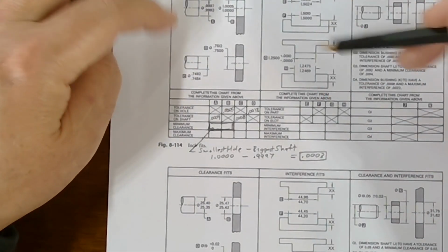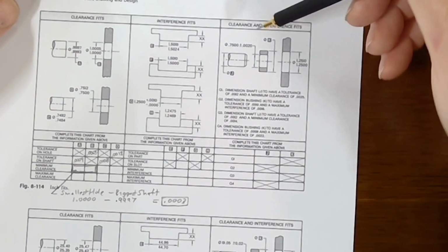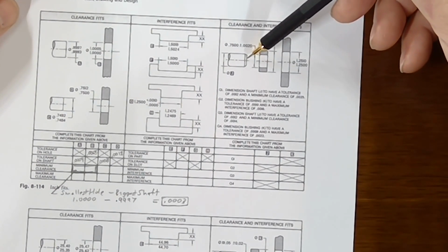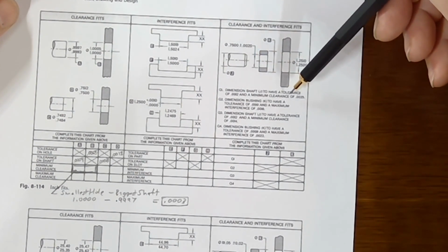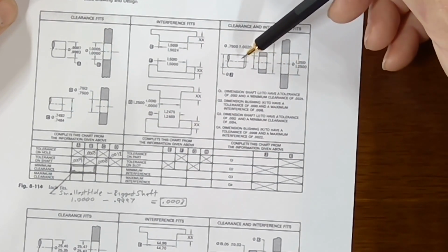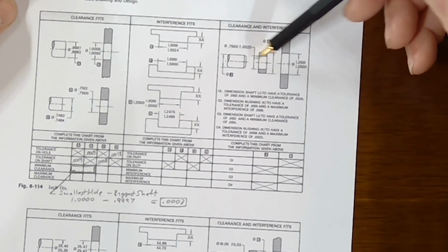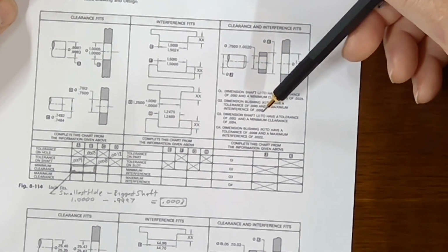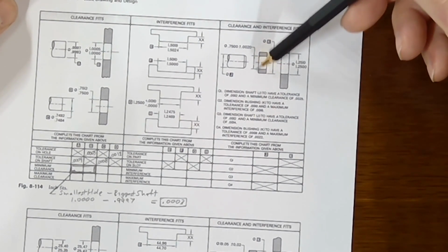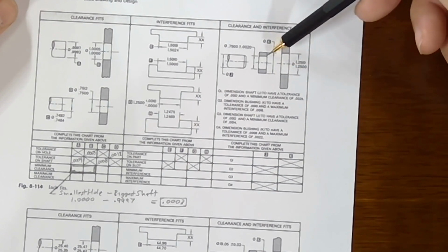Can you do those? Those are pretty straightforward. I don't think anybody will have too much trouble with these. Now this one's kind of hard because you're taking this guy and they're talking about clearance on J. So this shaft slides into this thing, and there's a clearance between these two parts. Then K, they're talking about interference. So this little donut thing presses into this hole over here.